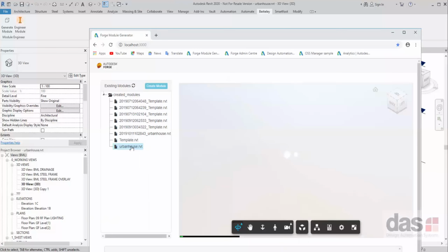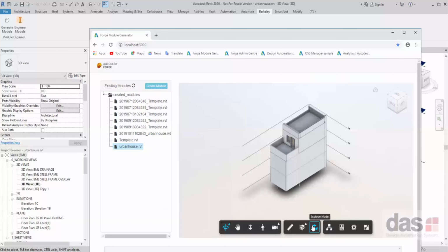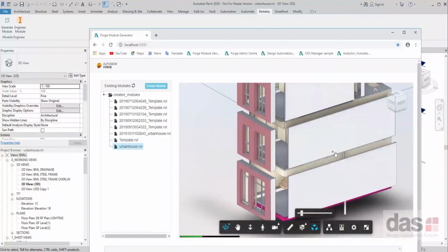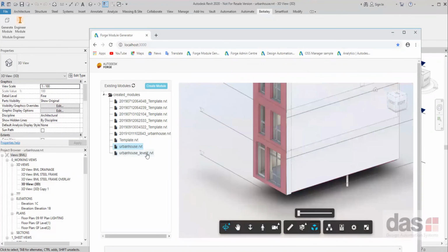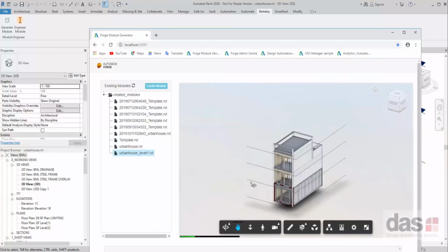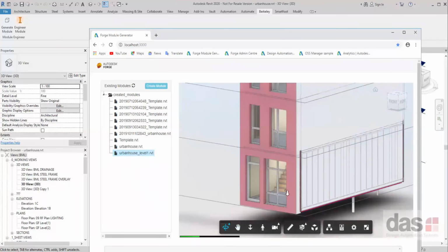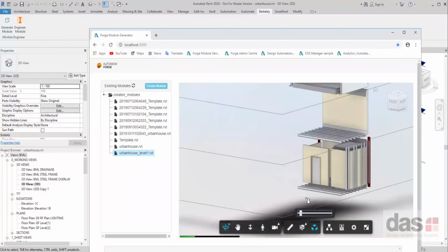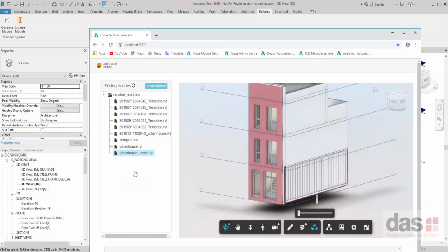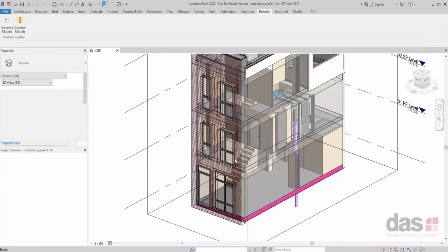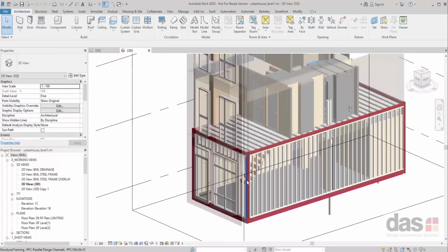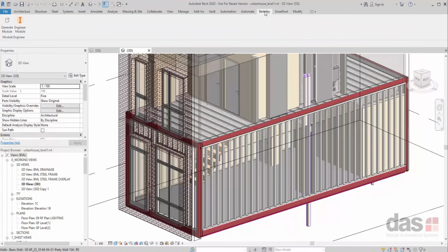a cloud-based environment. So now you can start to see here's that same model. You can see it in the Forge viewer. And what this automation is able to do is take one of the levels and generate the framing for that one level in that one room. So now you've got a complete framing for that. You can see it in the viewer, again, because anything that's RVT based, you can extract to a viewer. And then because it's actually an RVT, you can download it and link it into the original model that you had. That means that now you see that same model fully framed in Revit. So you can understand the impact of design decisions directly here.